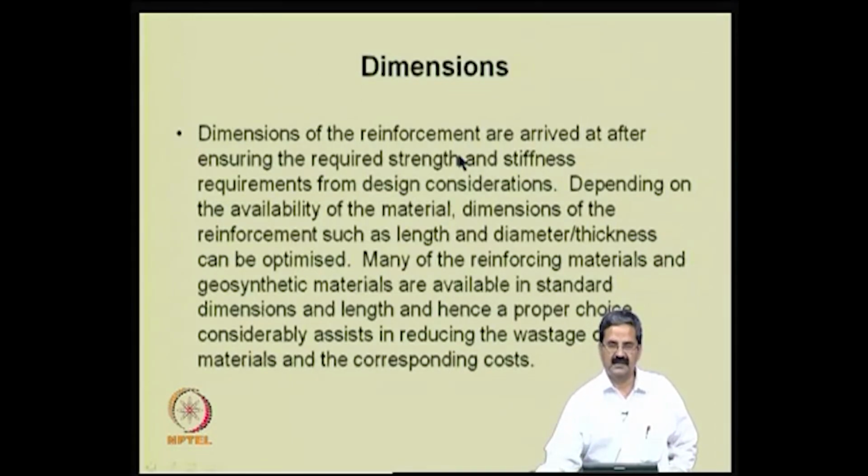Another important thing is, the other day I was mentioning, you have a geocomposite also. Geocomposite means it has tensile properties as well as drainage properties. Depending on the application it may come in different shapes. Many of these things come in rolls, and you need to know how many rolls are required. If you ask a company, he will ask you, sir, how many rolls you need. He will not ask what your design is and all that. He would be only interested in the number of rolls required.